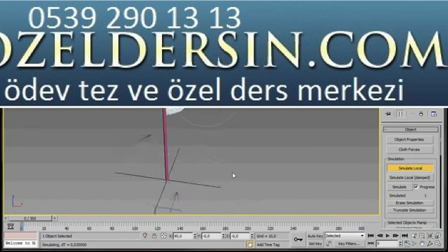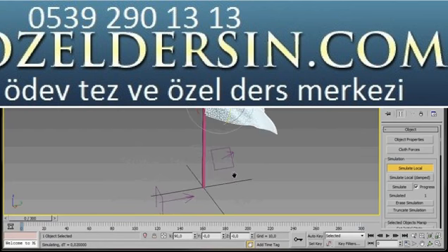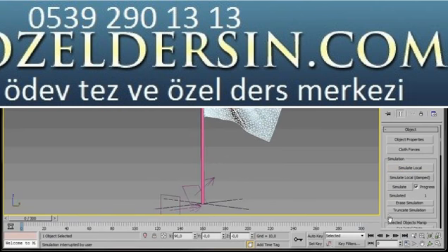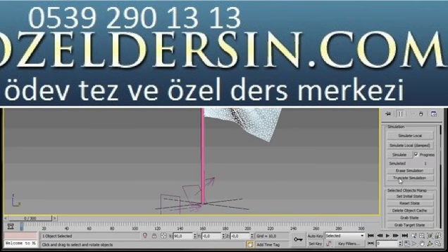Let's orbit around. I'll use the middle mouse button and hold down the Alt key on the keyboard. Let's turn off local simulate, and we're just going to scroll down to selected objects and press set initial state. Now this is going to be our first frame for our simulation. Let's just scroll up now and press simulate. Here we can see our dialog has popped up.